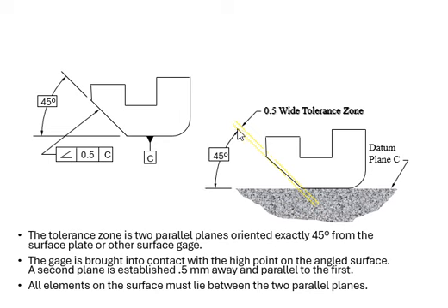And of course the variation of the angle can go from here all the way to here, and that is your tolerance zone, which we put in your control frame regarding that angle. So we're showing a little angle symbol right there with a leader line, so you don't make a mistake where that angle is measured, from that surface to this datum plane, and that datum plane is controlled by datum C in this example.